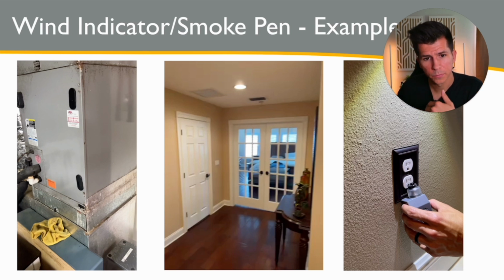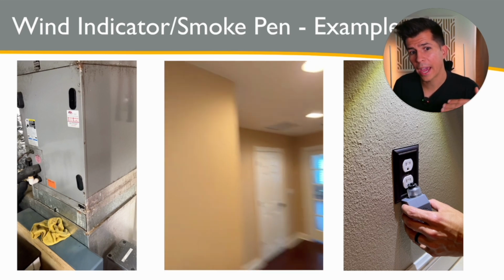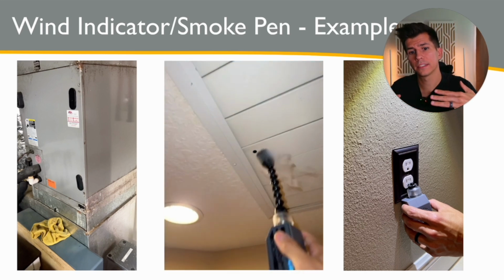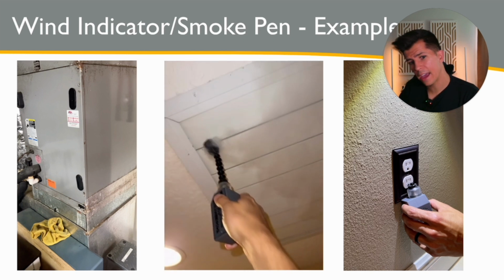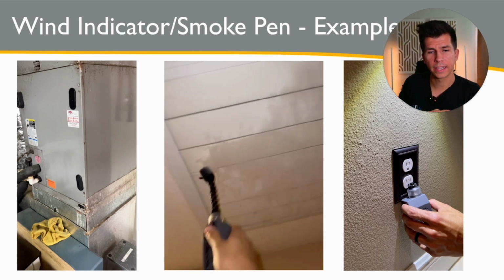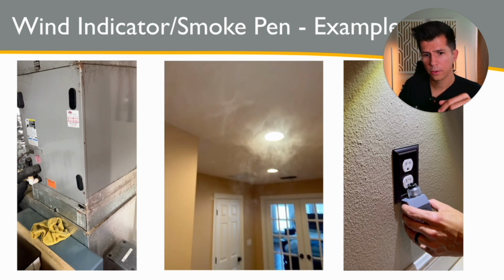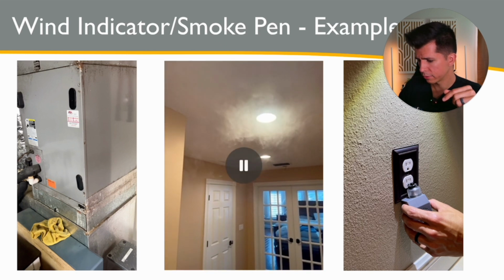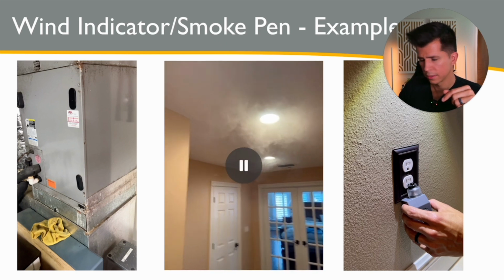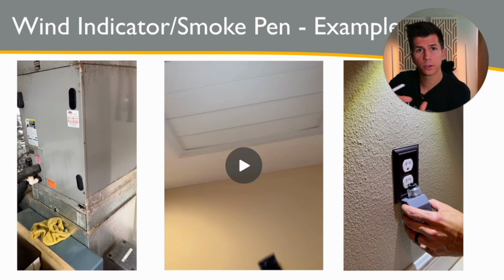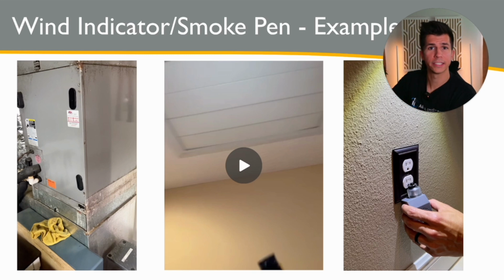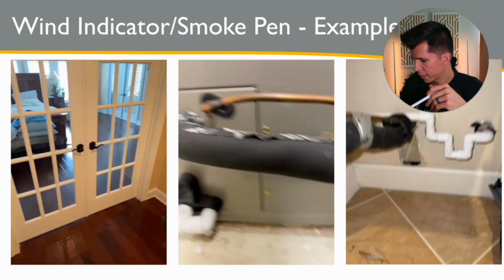So what's happening? This house had one of those old attic fans, like the whole home ventilators that they never sealed up. And check this out. That return is sucking air out of the attic. And guess where it's going? Oh, look at the direction it's following. Right here where the mold growth was. Right on the ceiling where the mold growth was. Why? Because that hot, humid air is passing across that cold drywall and causing condensation as it goes into the return. What about this one?